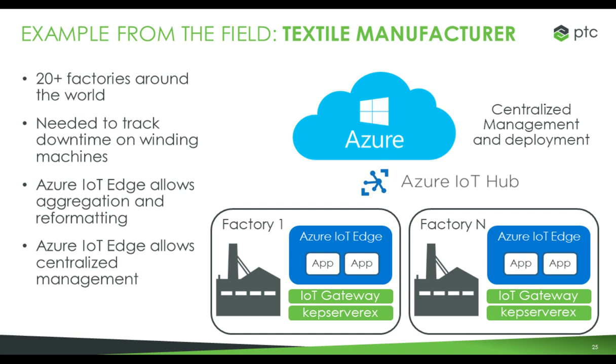Yeah, no, you summed it up pretty well. What I thought about when you started talking about standardization is, I admire the controls engineers that go out there and take the time, because I know how difficult it is updating, say, a work cell that consists of several PLCs, several drives, an HMI, and all that kind of stuff. They really try to standardize, assigning the same IP address ranges across the different devices, but then put something like a Moxa in front of it that could do the network address translation, and it maintains that. And we're trying to achieve the same thing on the IT side. You've got to standardize. That's like 80% of the battle that I've been seeing.